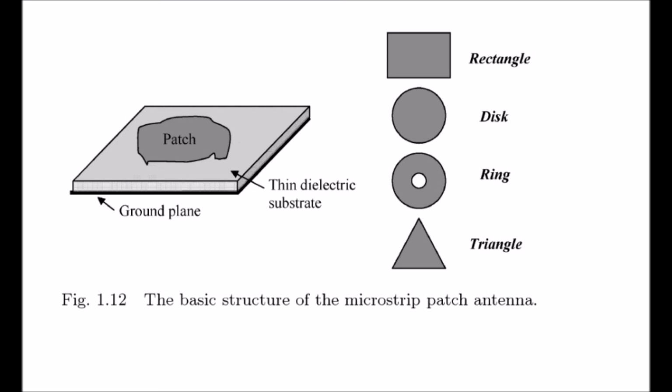Number 1, those having a relative dielectric constant, relative permittivity, in the range of 1.0 to 2.0. This type of material can be air, polystyrene, foam, or dielectric honeycomb. 2, those having a relative dielectric constant in the range of 2.0 to 4.0. This type of material consists mostly of fiberglass reinforced Teflon.